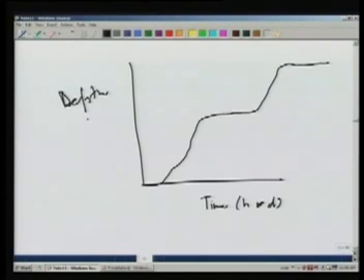So this shows the accumulation of rain in the rain gauge over time, and if you look at this curve, it tells you that there is no rain from this point to this point, there is some rainfall. The slope of this curve will show you the intensity of rainfall. So wherever the slope is largest, for example here or here, the intensity of rainfall is very high, and where it is flat, there is almost no rainfall or very low intensity rainfall. So the mass curve slope will give us the hydrograph.